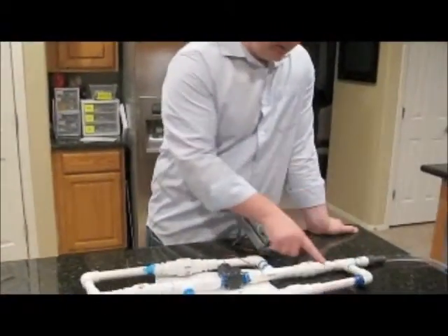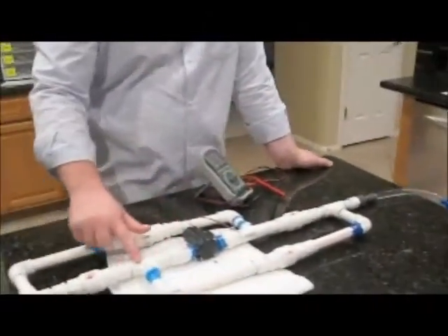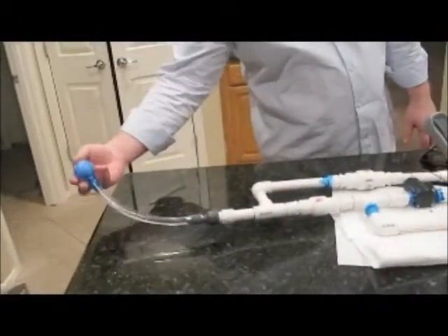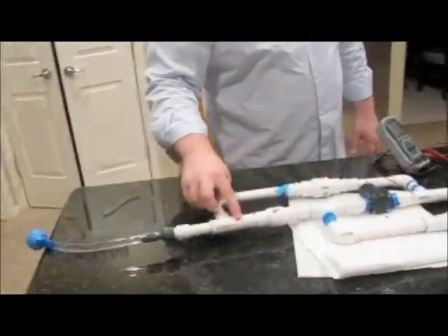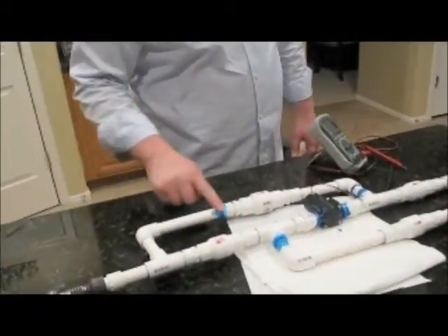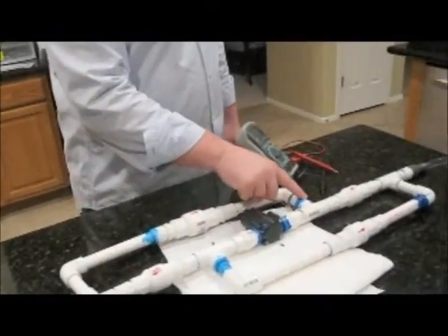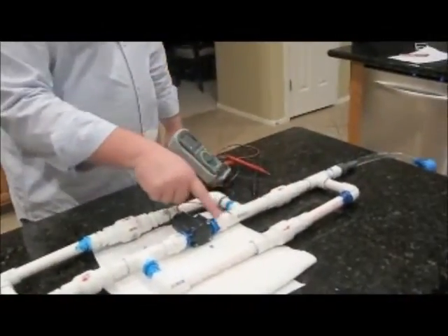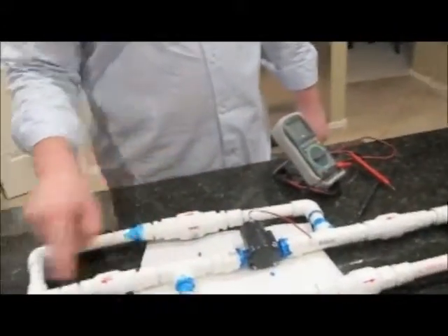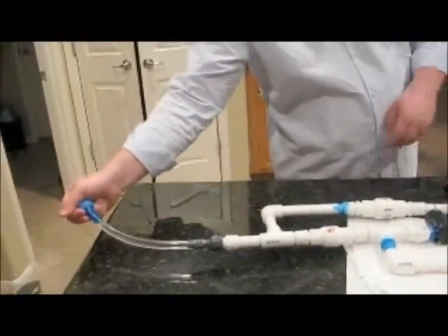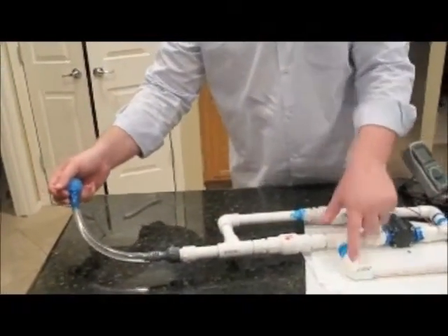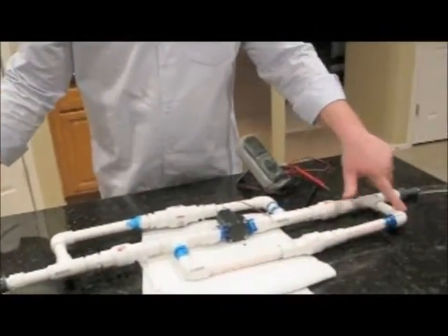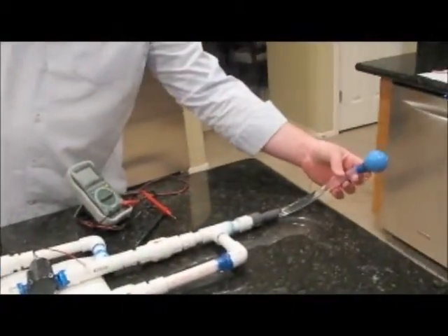So, as the water flows through here, it goes through the generator and over into this other bladder reservoir. And then once this is compressed, the water flows back, and the one-way check valve forces it to go through this path, and then afterwards, this one-way check valve forces the fluid to flow back this way. Since there's still pressure on this sac back here, the back pressure will prevent fluid from flowing again through here, and it'll instead divert through this path, which will lead it back to the other reservoir. So that's how the loop will be completed.